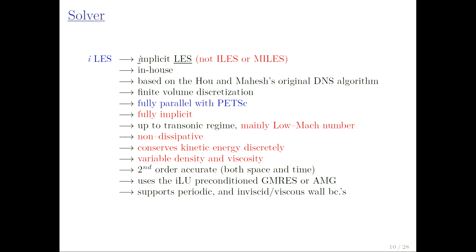This is an in-house solver, as you understand. I made it fully parallel with PETSc. It shares the same features as the numerical method. Additionally, I solved the linear systems arising from the discretization using incomplete LU preconditioned GMRES, which is an efficient approach.